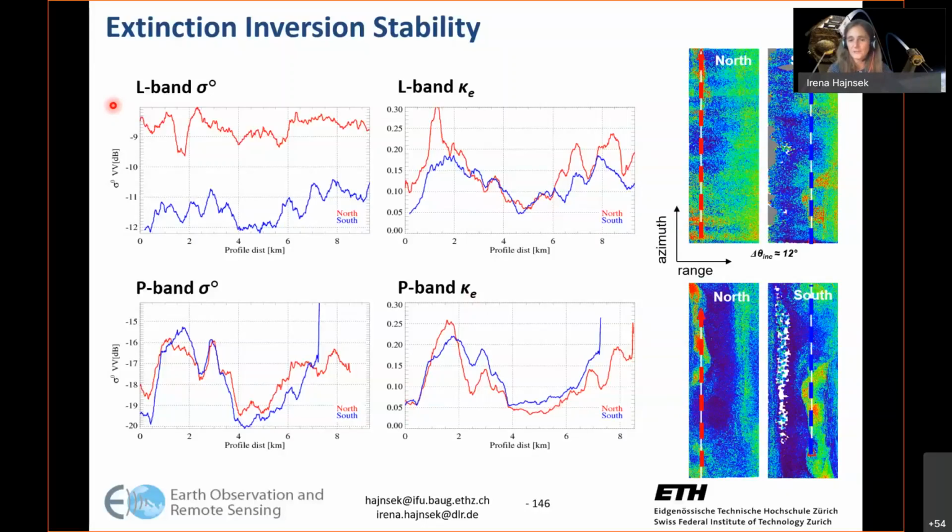And over this Ostfauna area, there is not only a snow area, but we have a very, very deep ice area too. The ice is going down to around 500 meters or even more. So we are not seeing the 500 meter depths. What we are seeing is actually only the interface of snow and ice, and then something that is, let me say, blurred out because we are not reaching the ground completely. So we have an infinite volume, you could imagine, where we have no ground contribution.